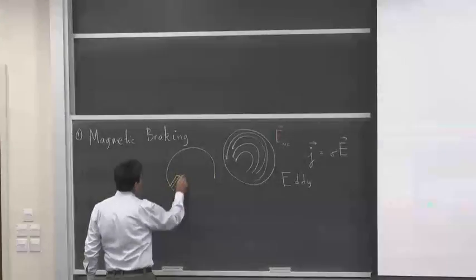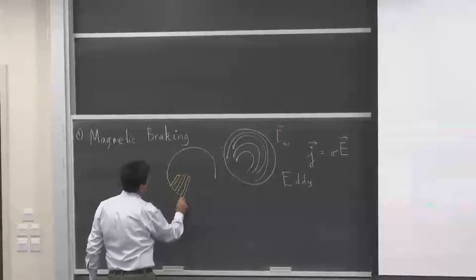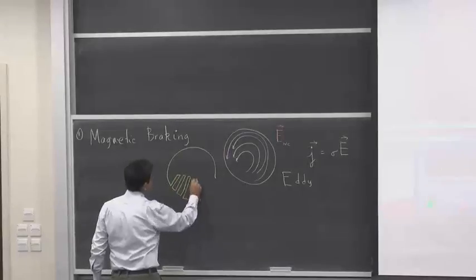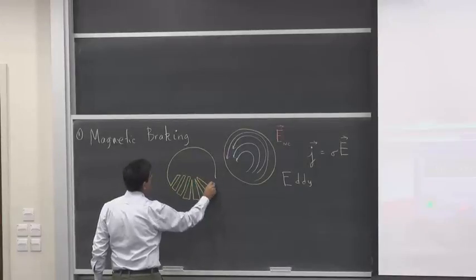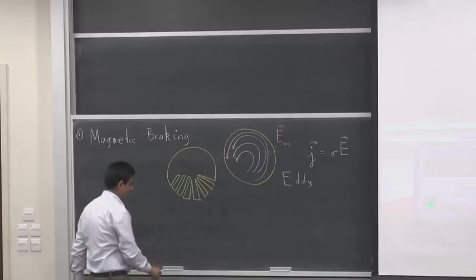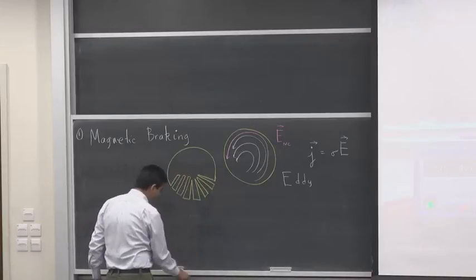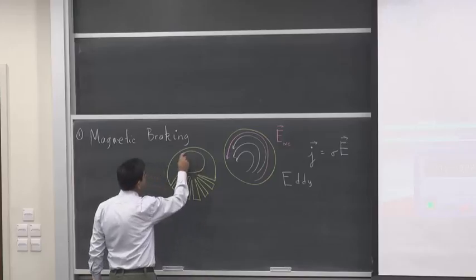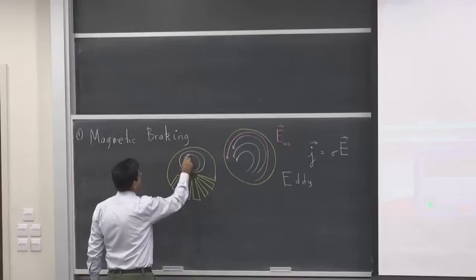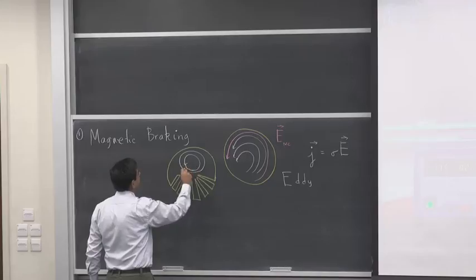Alright, so now I have another kind of disk in which eddy currents will no doubt be produced, but this disk has been variegated, which means that in the lower semicircle, the lower hemisphere, it has these incisions. Eddy currents may only flow through a closed path. They have to flow through closed paths. They can only pass inside this region. So this will be the direction of the eddy currents.